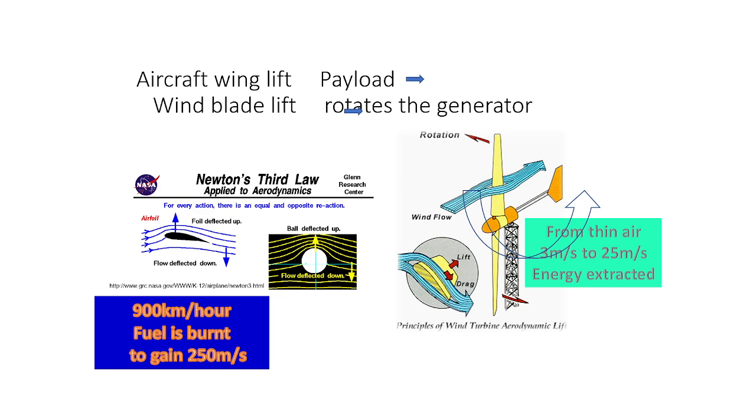So when such a thing happens, we start applying the brakes applicable for the rotor. It may be a disc brake like what we have in our car, which will stop the rotation and then resist the cyclonic wind speed, which is 100 kilometer per hour and beyond, 25 meter per second.